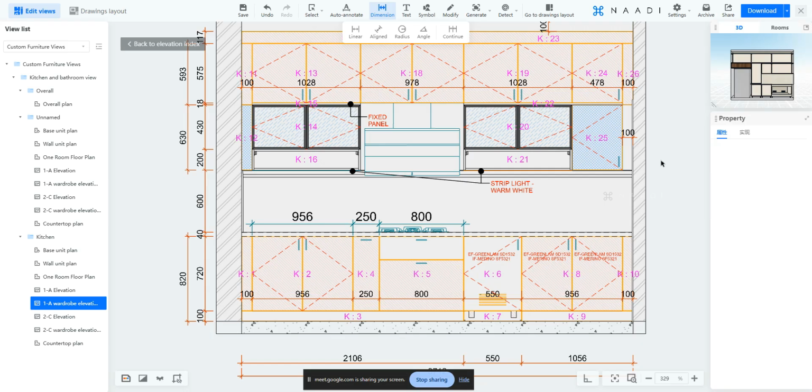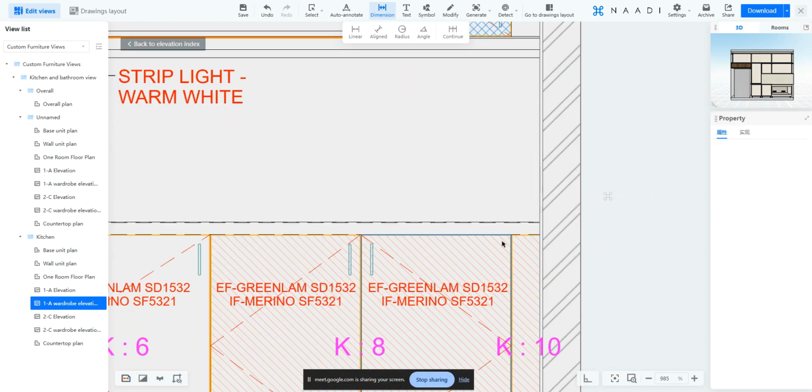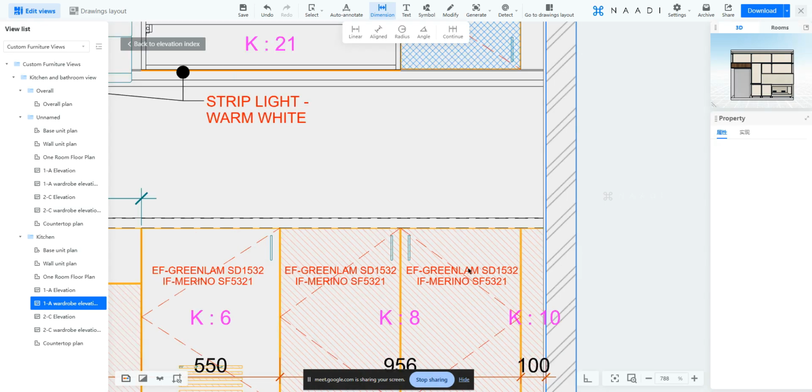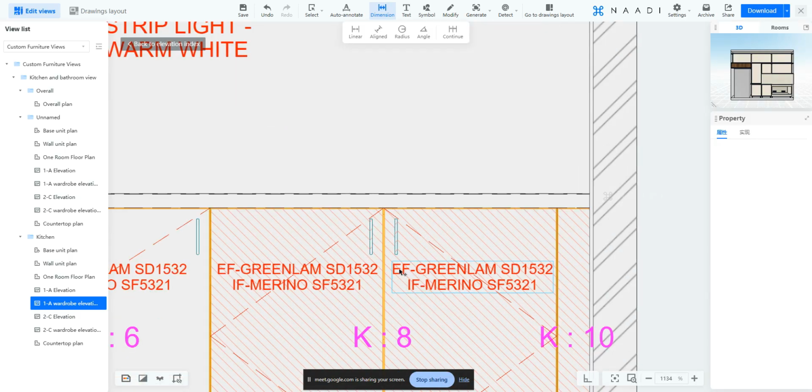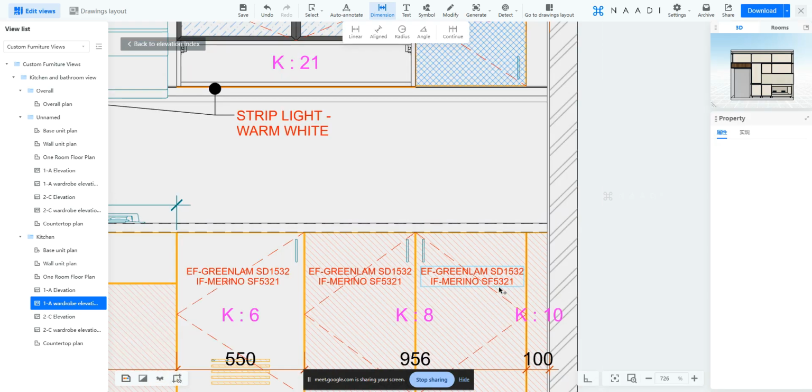Fine. That is a very unique requirement, which is not at all in the industry standard for home drawing. What you're mentioning is that you want to mention the edge band and everything in the drawing here, right? Please do it in the leader itself. I noticed some organizations mentioning the external finish and internal finish as an annotation here. But I've never seen an organization mention the edge band finish and everything in the annotation too. Because if that is done, the text itself will cover the majority of the shutter, so your design might not get communicated. So in those cases, please mention those things as a leader.